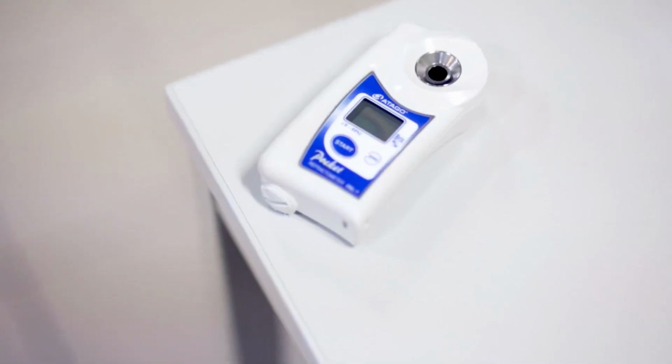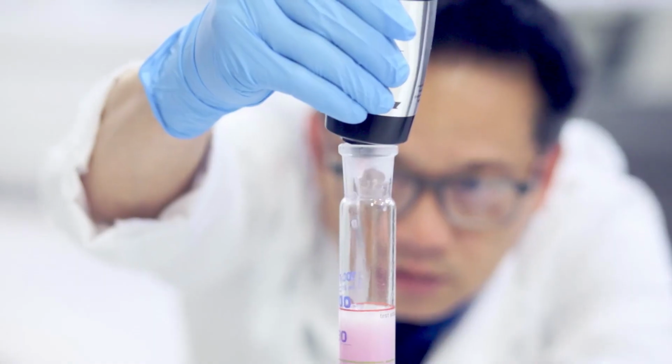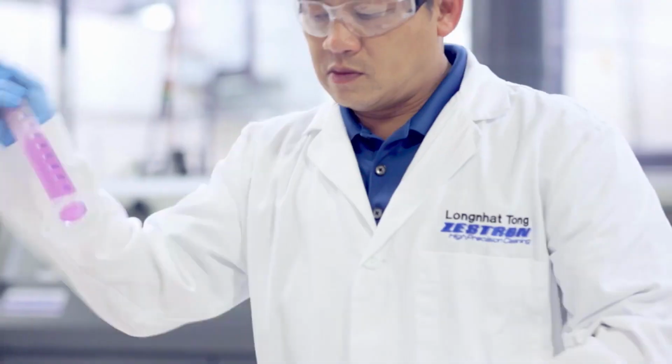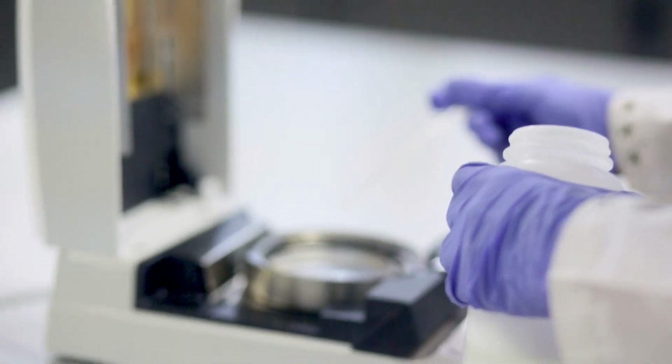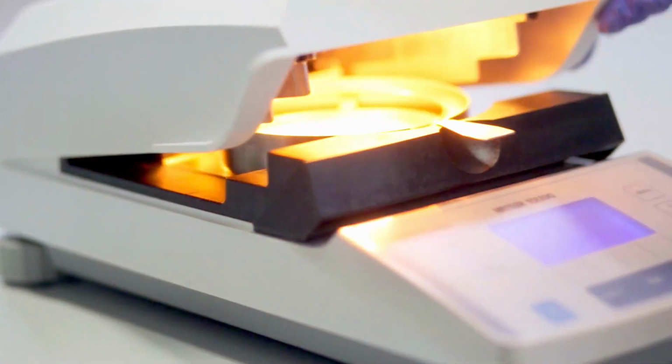We could take a look at the concentration level of the cleaning agent, which could be measured using a refractometer or a chemically targeted phase separation test method, or also based on some other sensing technologies. Furthermore, we can look at the pH level of the cleaning agent as well as the conductivity level, plus an NVR, which stands for the non-volatile residue detection.